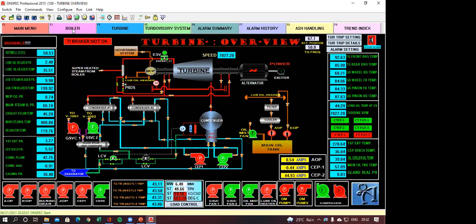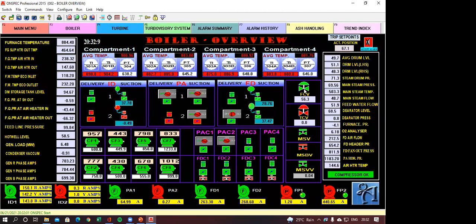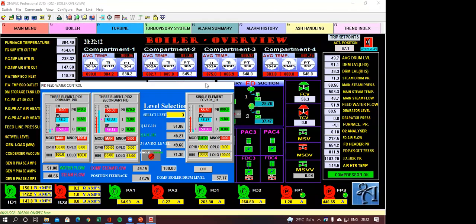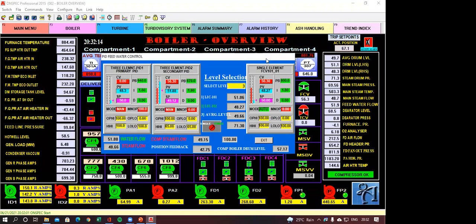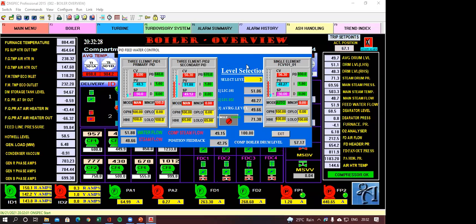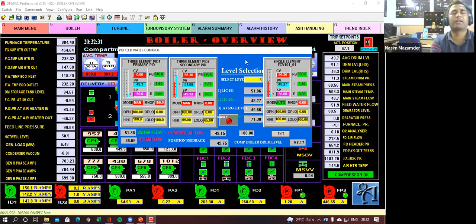So is there any method or written calculation or a few parameters to observe so that we can do PID tuning directly without any trial and error? Because if we change P, we need to give near about 5 to 10 minutes to observe the changes. Then we have to change I, then D. Yeah, definitely there are some calculations, but the calculations will give you more complex things. So PID setting is definitely based on your trial and error method.